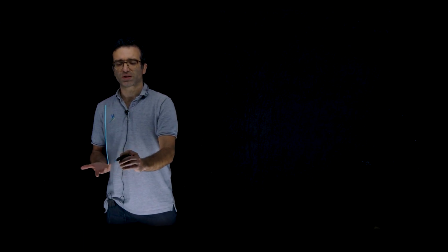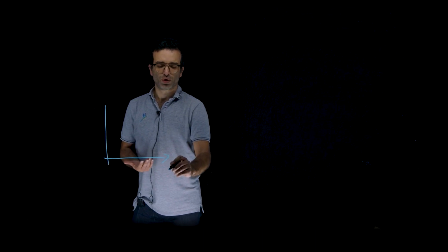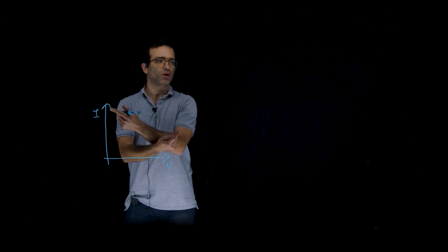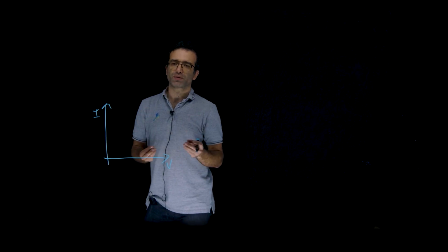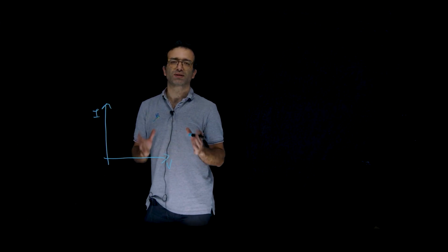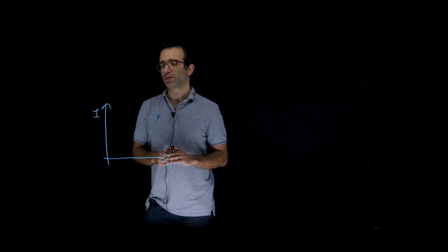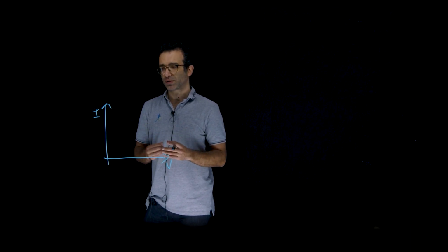All right, so the question here is how do we measure a SQUID? Until now, when we measured a device electrically, we never asked ourselves the question, do we impose a voltage and measure a current, or the other way around? The reason for that is that most of the devices that we measured are linear. But in the case of a SQUID, the IV characteristics are not necessarily linear, and it depends very much on the characteristic of the SQUID.